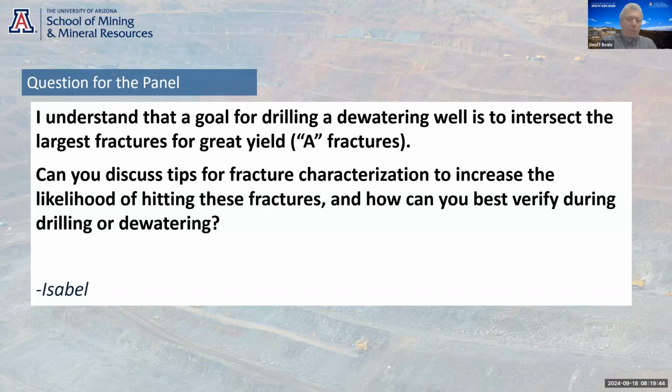Particularly where you've got an initial site investigation where you don't understand the fractures. Once you know the site and you have a little bit more confidence that the fractures are homogeneous or they're consistent, then you can maybe drop the pilot holes.